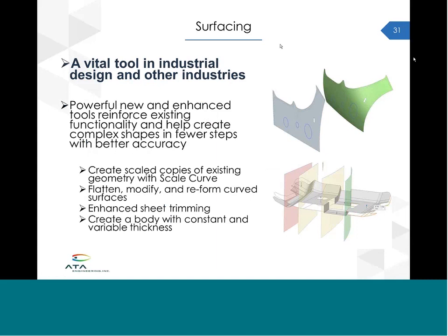Now when it comes to surfacing, the image at the top right illustrates this new feature that allows you to flatten a surface and then reshape the surface to its original curve. What you don't see in this image is perhaps the original incarnation of the surface before it's flattened. But now you can take surfaces, flatten them as you see in this gray sheet body, then you can do all your sketching. You don't have to worry about tangent planes.